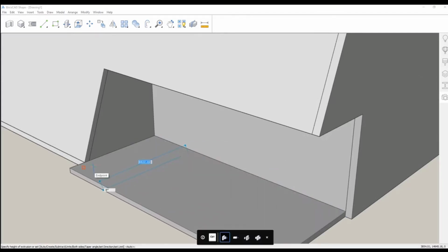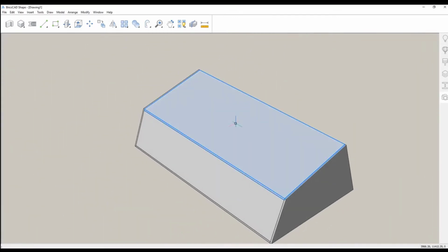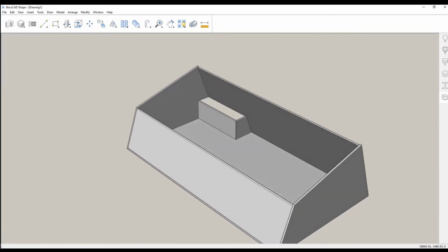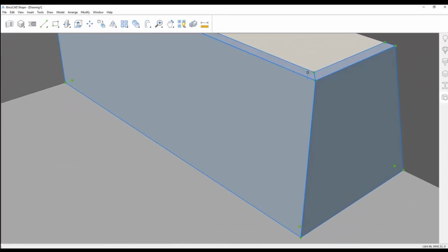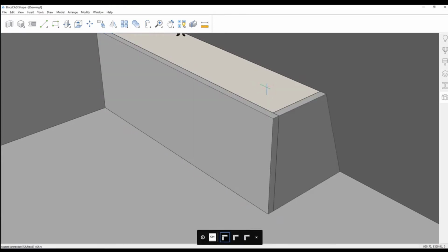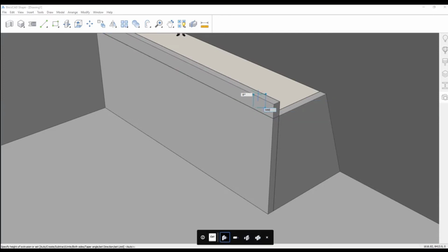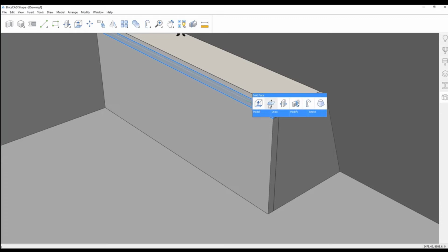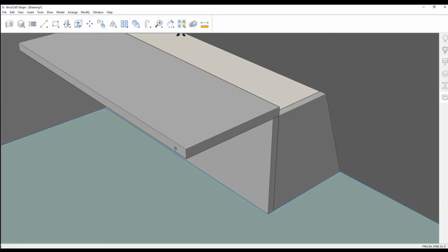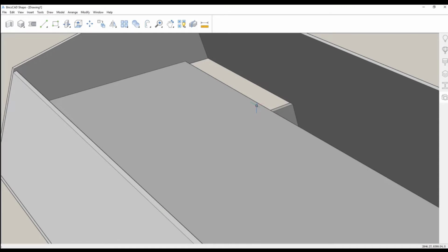Select the front edge of the slab as a new boundary and drag it out to create the floor slab for the entryway. Hiding the visibility on the roof, it's easy to change the way that these wall segments come together, bevel or butt. By using butt, we'll simply extract that top profile and create the floor slab for the first floor. Again, we'll drive those edges to the next solid face, and our floor is done.